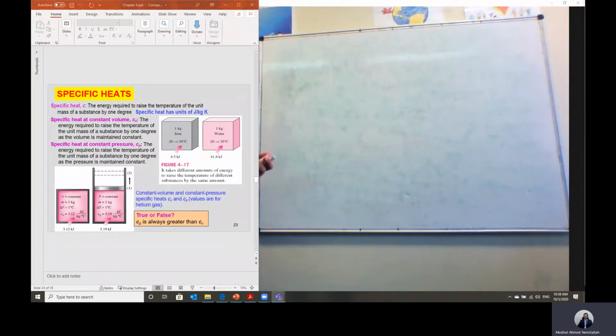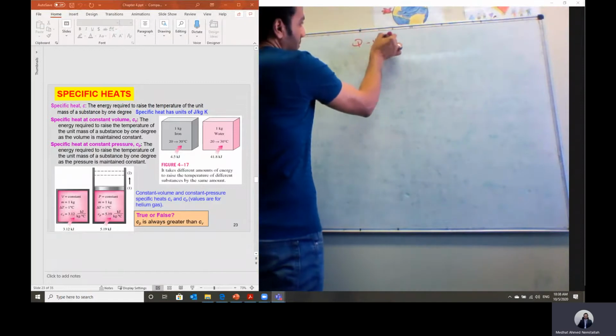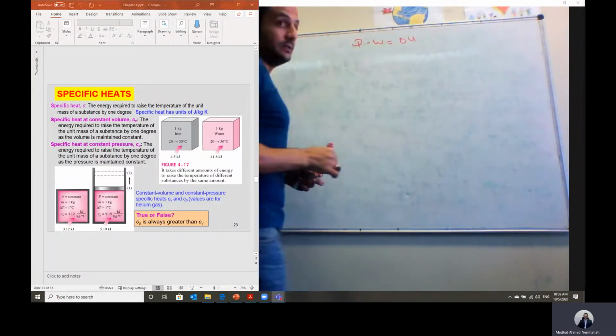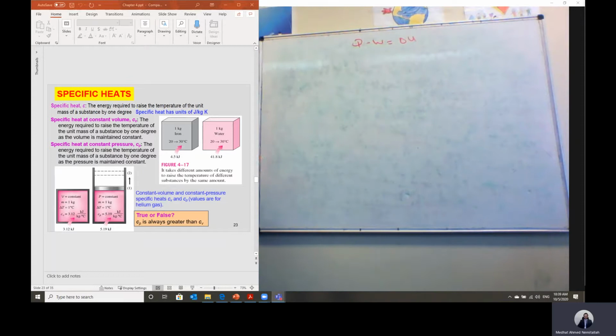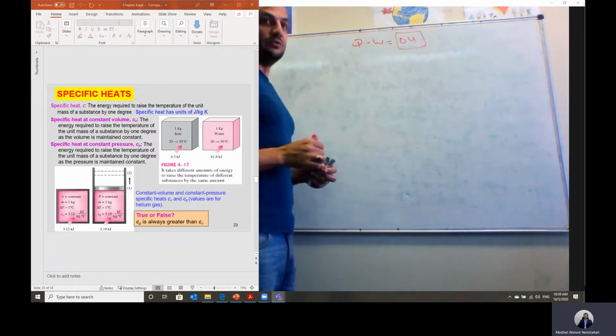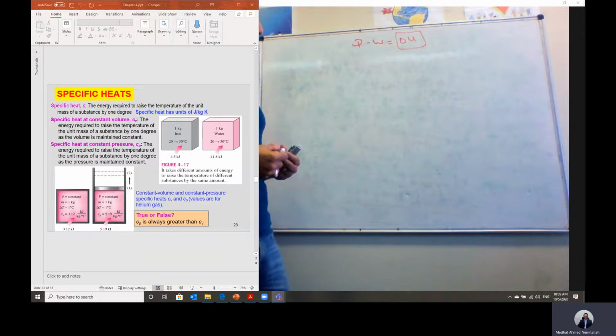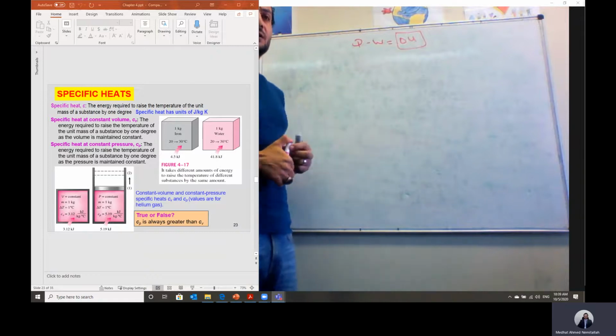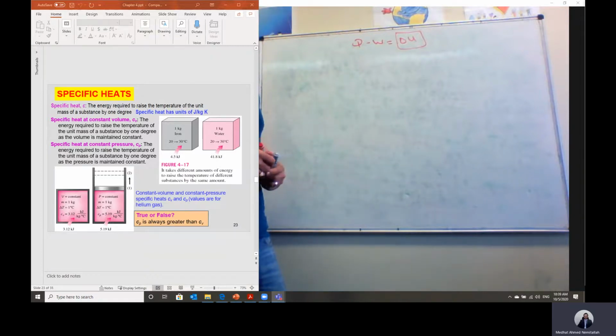Last time we talked about the first law of thermodynamics, Q minus W is equal to delta U. And we have seen some applications of the first law, how we can calculate the heat transfer and the work for any process. And we have also learned how we can calculate the change of internal energy, delta U, in case we have steam or refrigerant. In this case, we will be using tables. But in case we have a gas in this case.